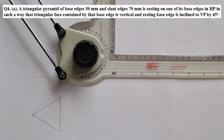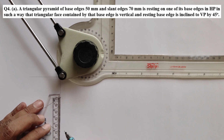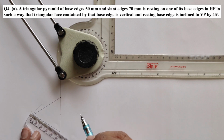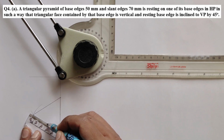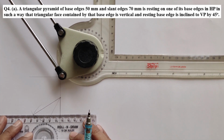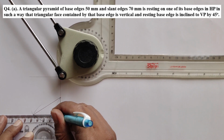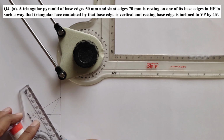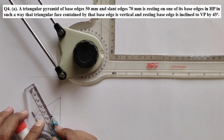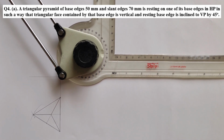Once you have completed this, you have to draw the slant edges. In order to draw the slant edges, you have to use the bisection method. The distance is easy, it is 50 mm. You can easily take the midpoint. You have to do it for 2 sides, and join them. Once you join this, you obtain the center, that is the apex in this case, and you have to draw these slant edges from each corner of the base up to the apex.